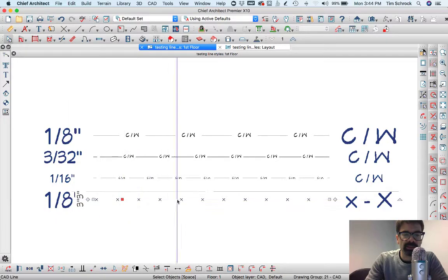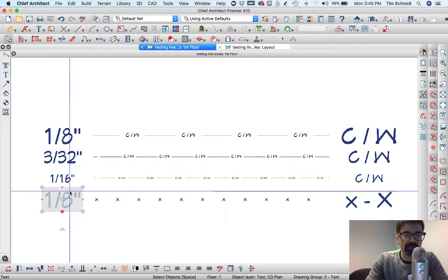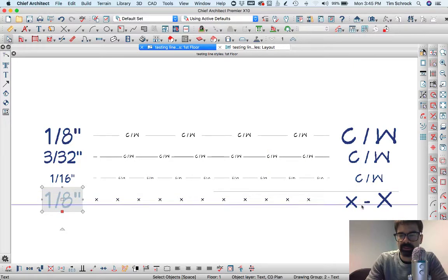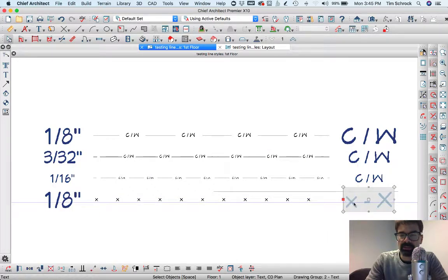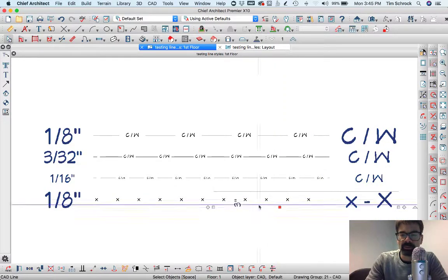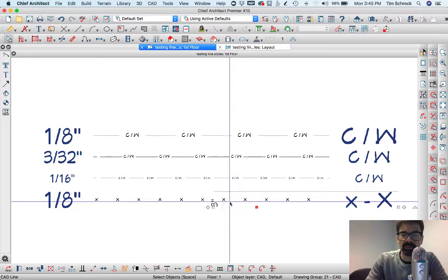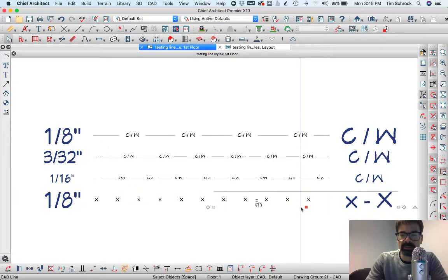Now this line type, my steel mesh, I didn't use capital letter X. I used a small x. So at 1/8 of an inch tall, text is to look like this height. And so I typed a small x versus a capital X. And I drew 2 lines 6 inches apart, so 3 inches off of the center line of this steel mesh. So 6 inches apart, and you can see the bottom of the capital X and the top of the capital X really are that 6 inches tall. So that when I send it to layout, this is what we've got.